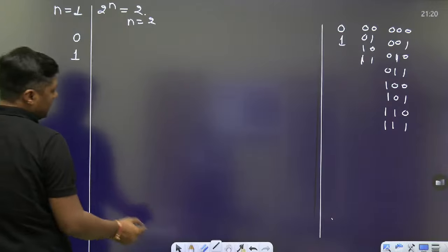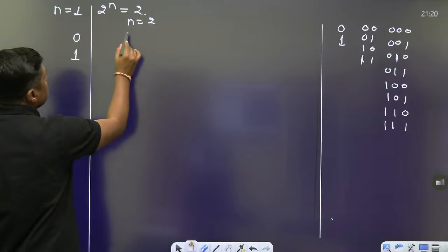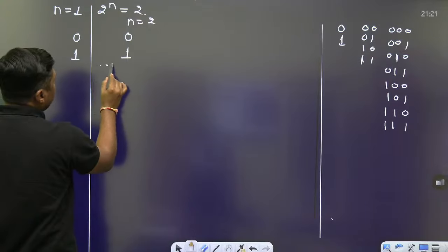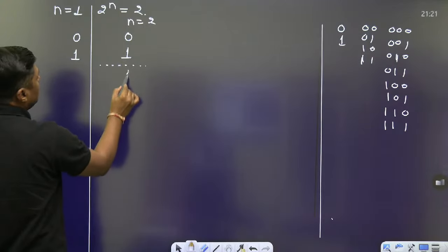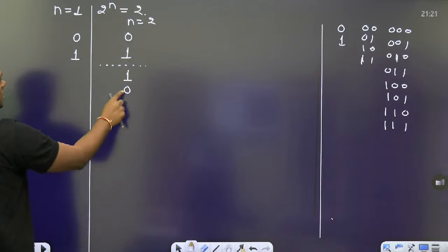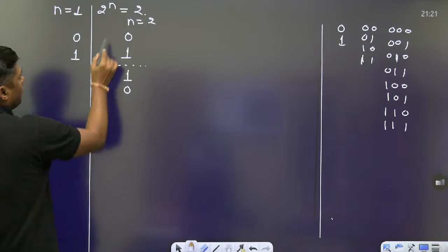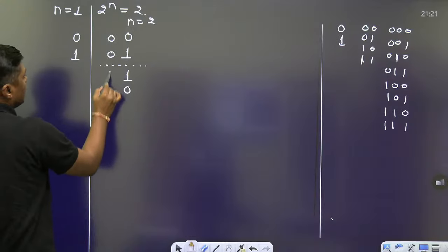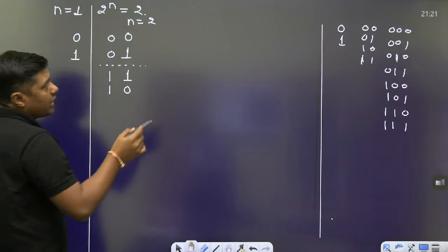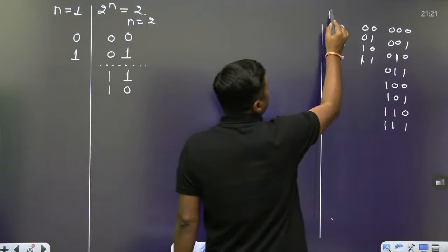If it is a 2-bit code, then always write like this: 0, 1. First of all, write 0, 1. Now, what is the reflection of this? 1, 0. What is the reflection of 1, 0? 0, 1. Mirror image 1, 0. This is called reflection. Now put a 0 here and a 1 here. And that is called what? Gray code. Now you can watch. What is the difference between these?